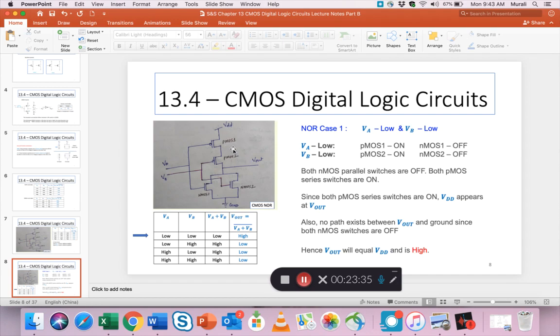So that means when this is on, the opposite transistor has to be off, and vice versa. If this is on, that has to be off, right? So let's check on that too. Now we already saw that they're both off, right? And more importantly, we have to check that whatever state they're in, these two also don't bring some additional voltages to confuse the issue, to bring some new stuff that doesn't logically apply, right? So what should happen to these?